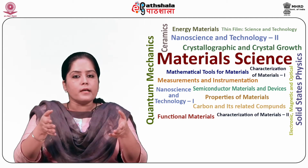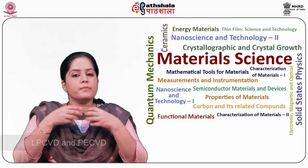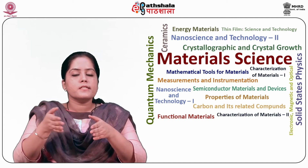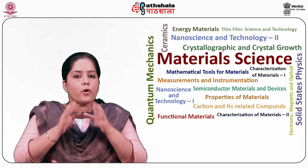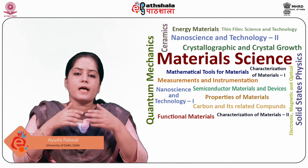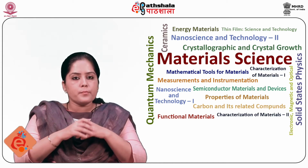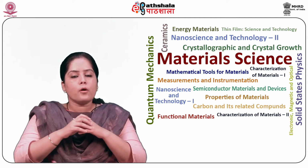The modern day chemical techniques like LPCVD and PECVD have been explained and their advantages over other conventional CVD techniques were discussed. The importance of the ALD technique in the deposition of thin films with atomically controlled thickness has been elaborated. The sol-gel technique is explained by a step-by-step process. Also, its economic importance has been described.